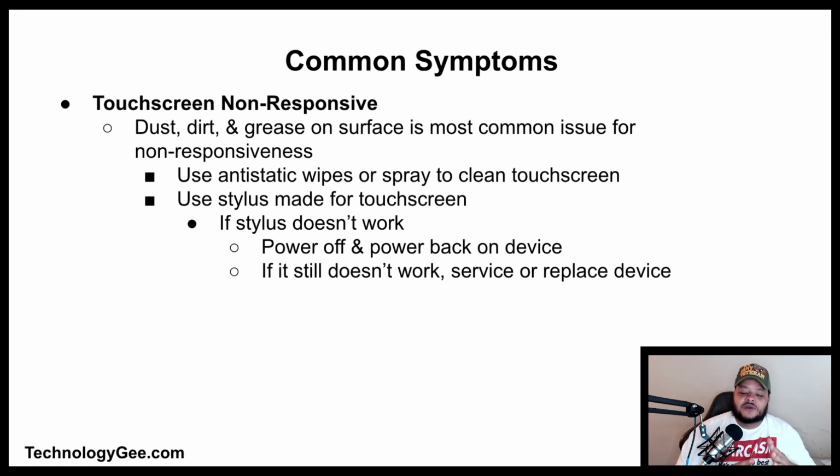What about touchscreen non-responsiveness? So dust, dirt, and grease on the surface of the touchscreen is the most common reason for why a touchscreen is non-responsive. So to fix this, you need to use anti-static wipes or spray that are designed for touchscreens to clean it. You need to use a stylus made for the touchscreen. If the stylus does not work, you need to power it off, power back on the device. And if the stylus is still not working, then you might need to service the device or replace it.